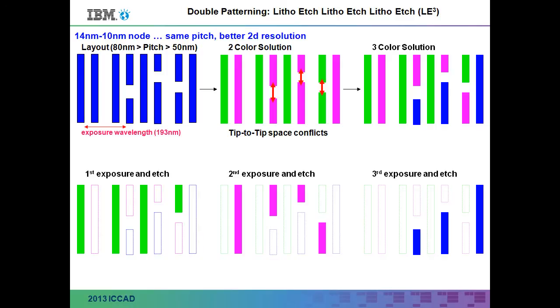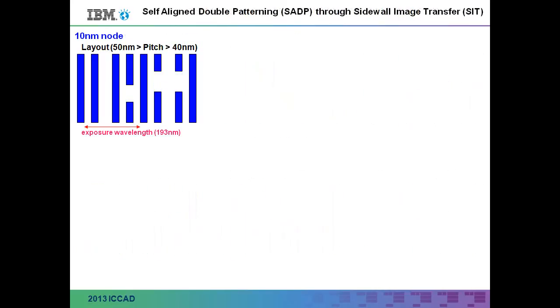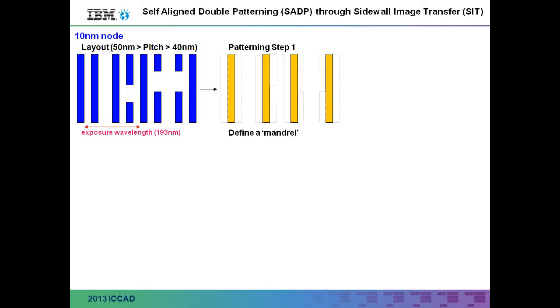All right, so then how do we get below 50 nanometers? If you want to cover this domain between 50 and 40, and of course there's no law that says you can't introduce these techniques earlier, it's just you can't really extend them further down. So the technique being used here is, for obvious reasons, called self-aligned double patterning, because it overcomes this misalignment, this overlay dependency on resolution.